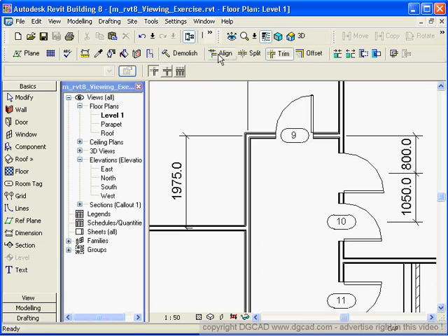I can go in and hit trim, and then you'll notice these again. Watch these change depending on what it is you pick. Okay, so always look down here. They're sneaky. You forget they're there. So trim, and I'm going to say this type of trim, and I can go here, and it'll do that. Okay, I'm just going to do an undo.